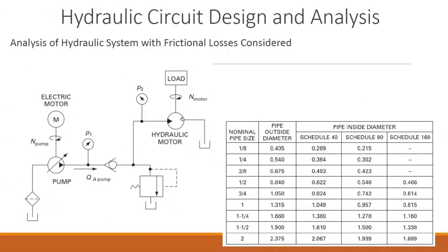A hydraulic motor is there, but it is one single direction, so the direction is given and it will be turning like this. So there is a filter, a tank, and a variable displacement, single direction hydraulic pump, which is run by the electric motor. The pump would push the hydraulic oil into the pipeline with the pressure given here, and then this is the check valve. This check valve would freely allow the oil to flow through it. It comes here, and now it has two branches, one is this one and the other one is this.